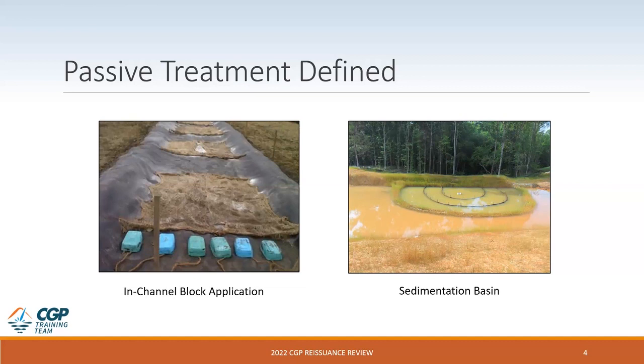There is downstream from that some jute matting, and essentially stormwater flows would pass through that channel. Some of the passive treatment chemical would then dissolve from those blocks and cause sediment particles to bind to the jute matting and then continue to flow through that channel.